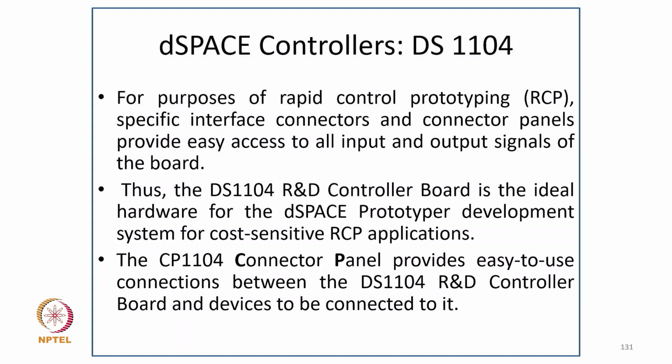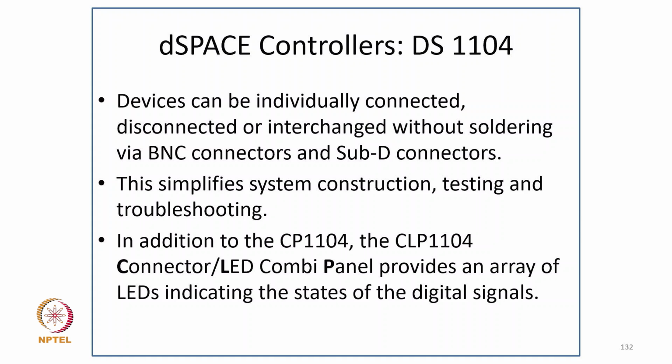DS1104 R&D controller board is the ideal hardware for the dSPACE prototyper development system for cost-sensitive RCP applications, and the CP1104 connector panel provides easy-to-use connectors between the DS1104 R&D controller board and the device to be connected to it. So devices can be individually connected, disconnected, or interchanged without soldering, via BNC connectors and Sub-D connectors, and this simplifies system construction, testing, and troubleshooting. In addition to the CP1104, the CLP1104 connector or LED combi panel provides an array of LEDs indicating the states of the digital